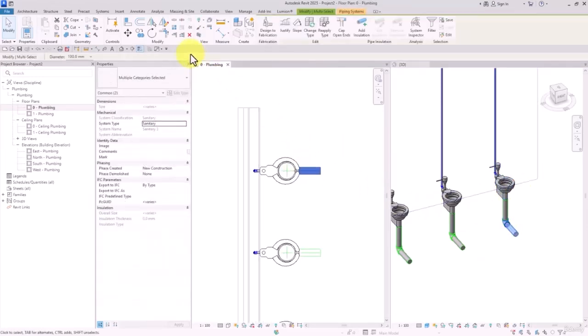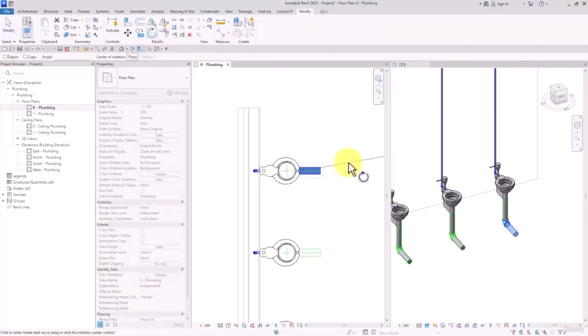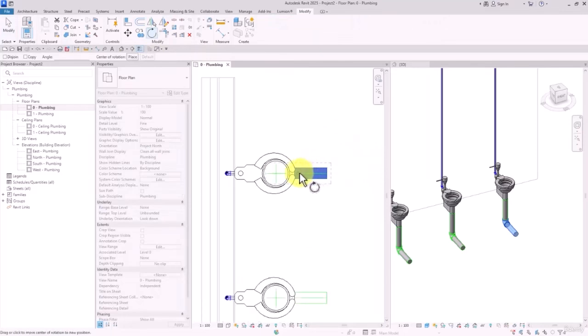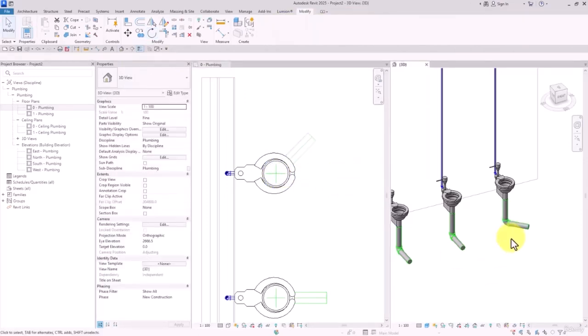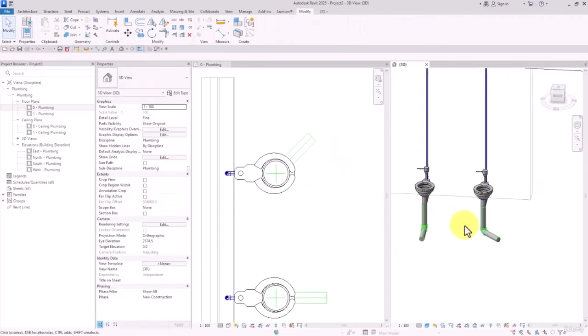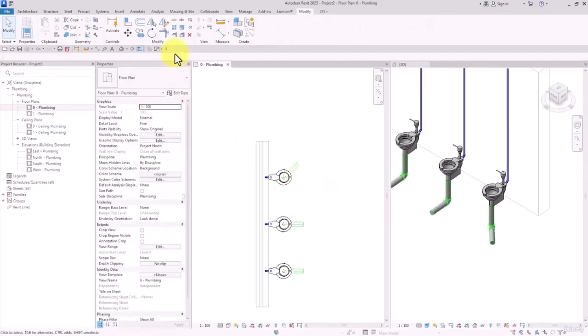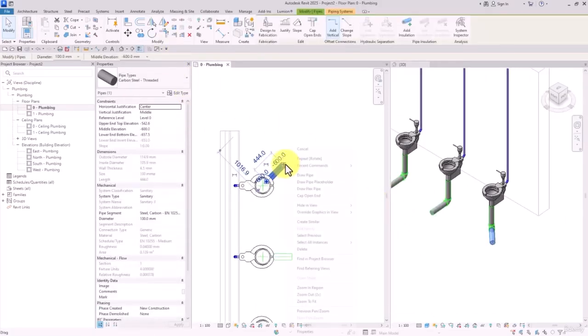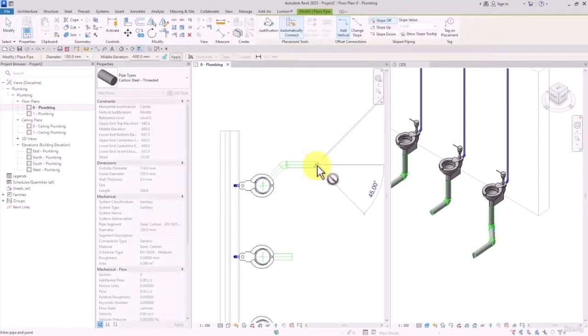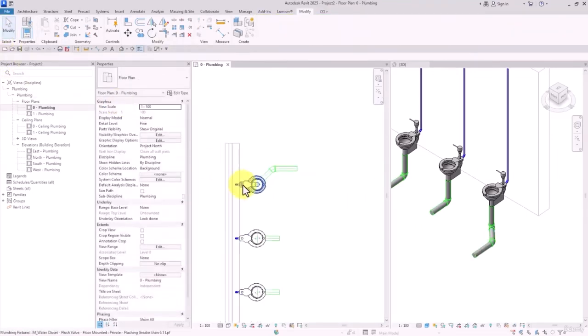Okay, I'm going to select this again, select Rotate. And then again, we need to select a base point. Click on Place first. And then select the base point and then rotate it, for example, by 45 degrees. All right, so this is rotate. After you're done with your rotation, you can continue drawing your sketches.